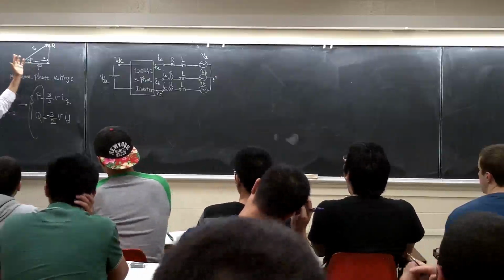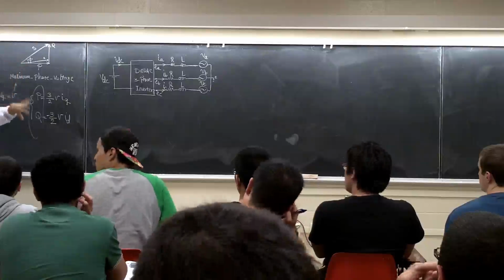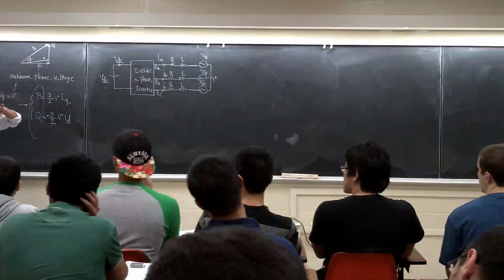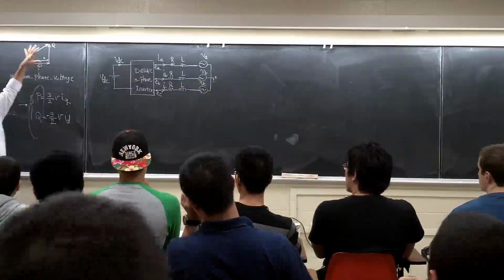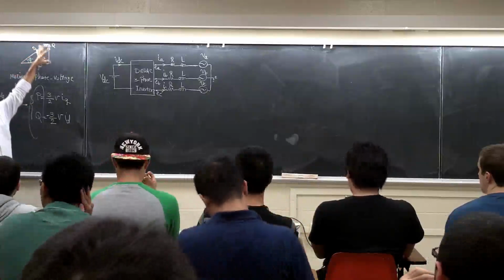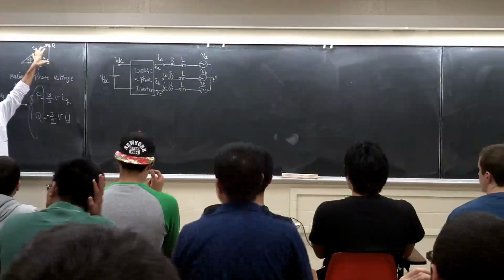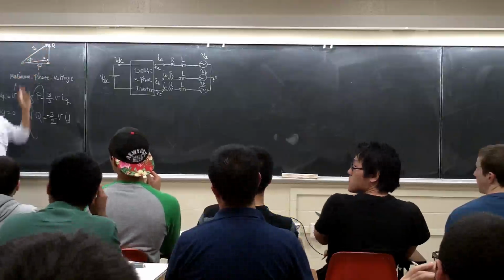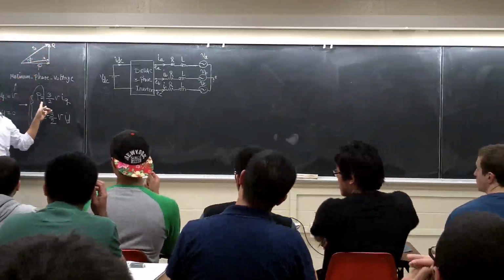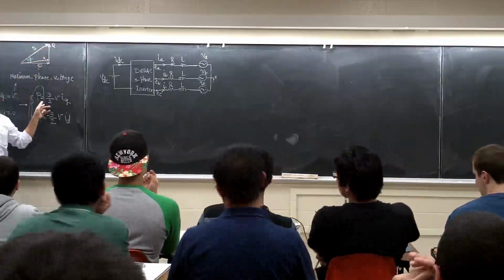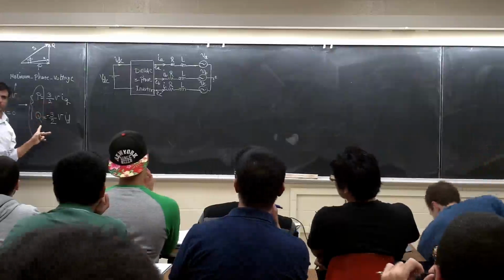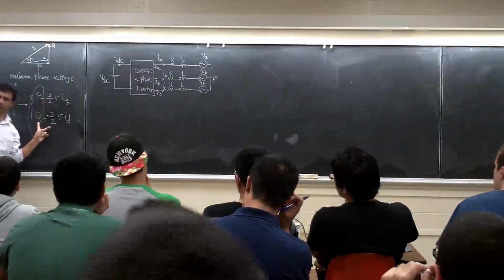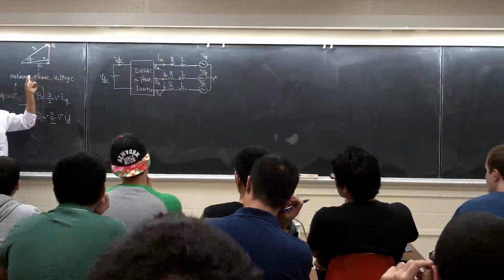Again, in the energy conversion course, one section we talked about was power factor correction, right? Power factor correction basically was, hey, let's reduce Q. I don't want to explain why we want to reduce Q, but basically we're trying to reduce the Q consumption, right? So basically, I want to charge my battery with whatever power I want. In this course, we're going to go with this one. Under how much Q? 0, because it's going to give me unity power factor, right?